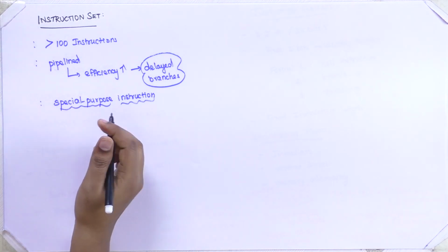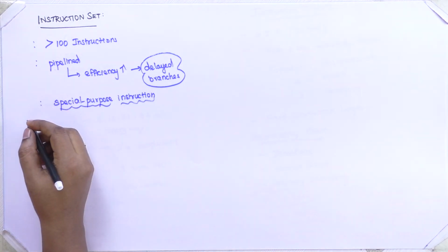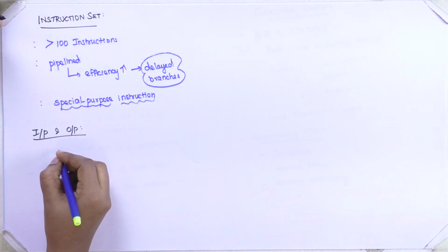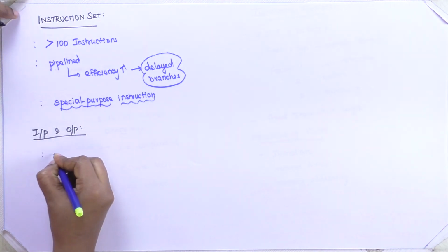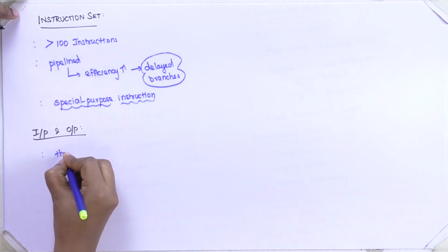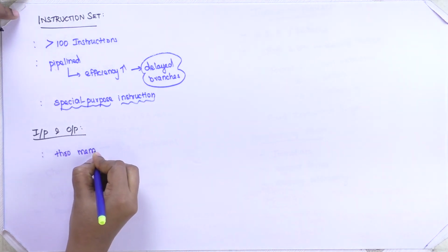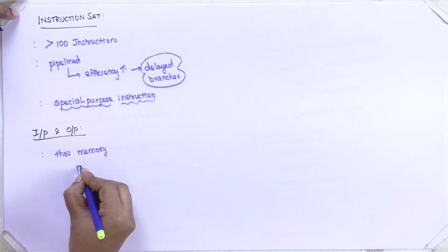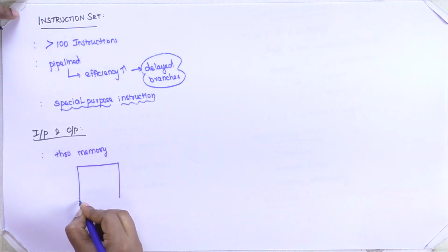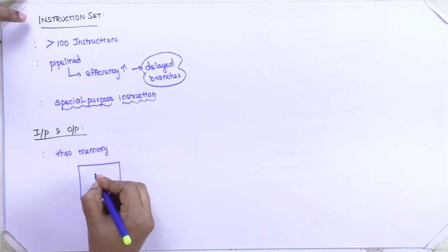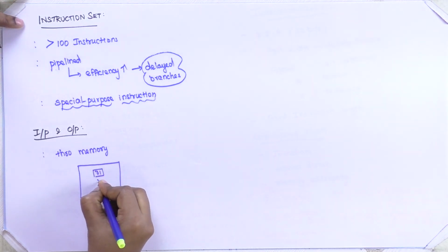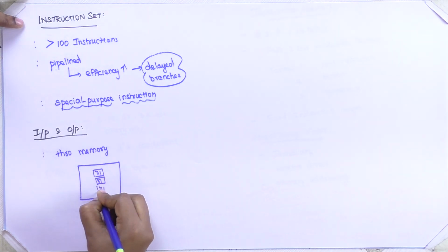The last hardware feature is input and output. Under input and output, communication with I/O devices is accomplished through memory. In memory, we have a range of memory locations which is logically replaced by device registers. That portion of memory is called the I/O space.